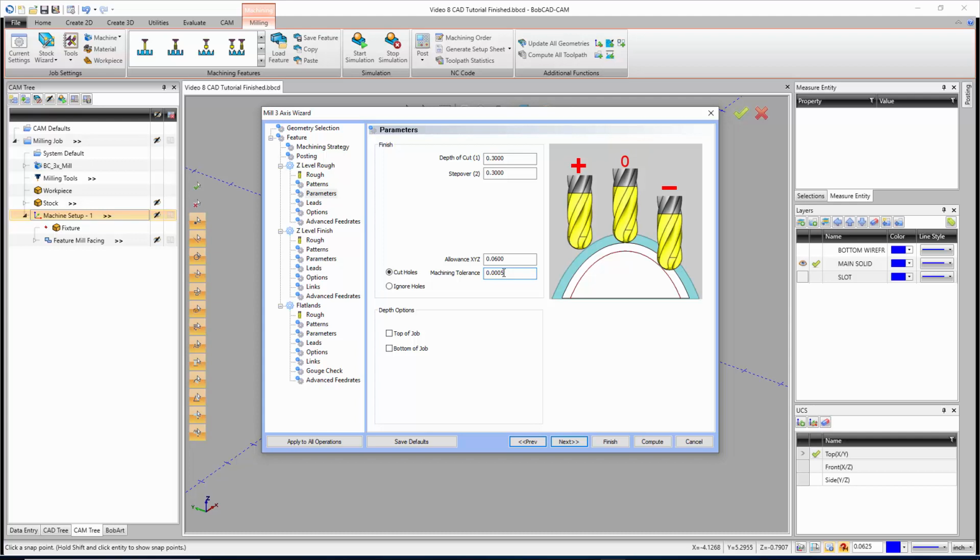If your tool paths are taking a really long time to calculate and the surface finish is already pretty good, you can try and turn it down to say 5 thousandths. That's going to calculate it faster, but it's going to give you a worse tool path. The other option is to make it smaller. So bring it down to a 1/10. This one's going to calculate longer, but it will give you a better tool path. So it is kind of worth it in some scenarios.